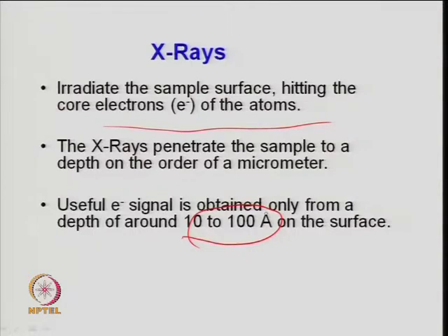So, the X-ray basically scans the surface, and during the scanning it identifies the diffraction at different theta angles, and then it tells about the crystal, because a crystal has a definite shape. That is where the diffraction takes place. If it is not crystalline, you will not get any peak, no diffraction will come.